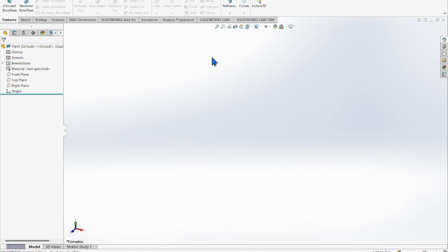To change our units, go down here at the bottom right corner, where you can change from millimeters, inches, centimeters, and meters. Since we're in the United States, we'll be using inches for now in this book, and we'll use inches every once in a while before we continue on with millimeters. Now, with the part itself, let's go to the sketch. Get the page going right here.